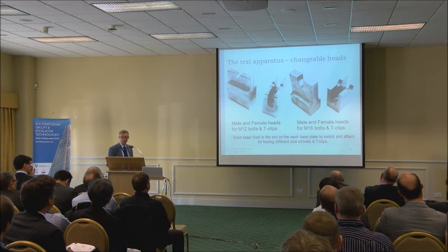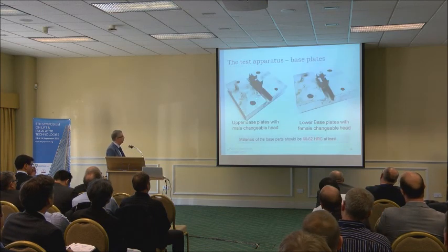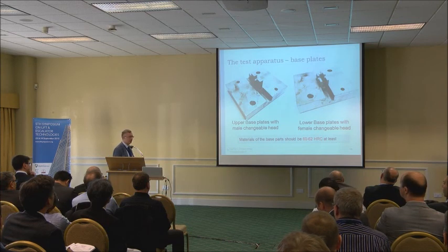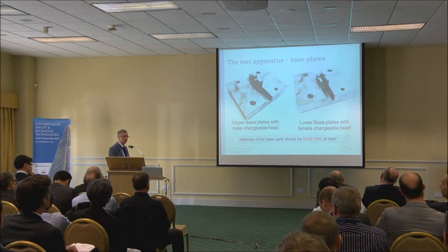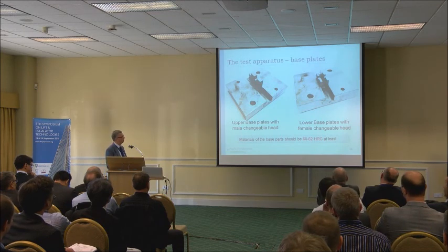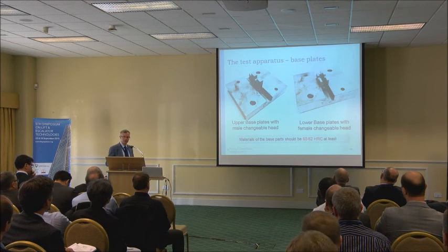These are changeable heads. We placed them in the upper and lower base plates and fixed them in the middle, so it is changeable. If you have a different size or diameter of T-clips or bolts, we may replace them with new ones, so we can manage to test.